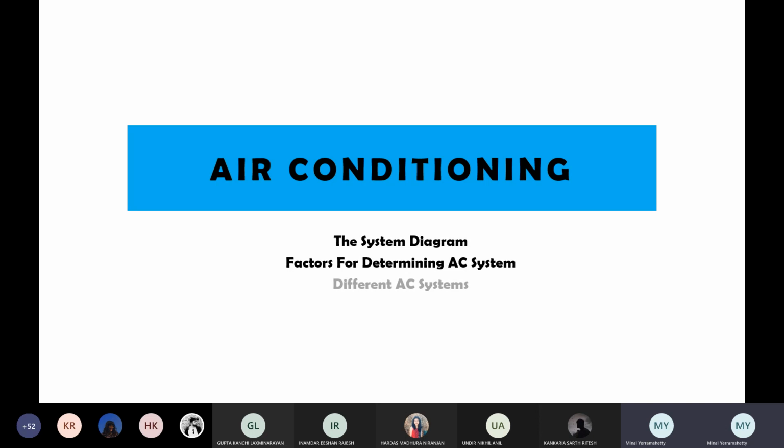अगर है तो आपको वो chilled water, which is the coolant, the degree of that water is around 6 to 8, 10 degrees. Okay, you need to take that chilled water to wherever respective places you need to go. Okay, where again the heat transfer happens, it gives away all its cooling to the AHU and comes back again in a normal form. Okay, फिर से वो ठंडा होता है, फिर से ऊपर जाता है, and that cycle also continues simultaneously, 24/7 if the building is working 24/7 continuous. ठीक है, तो ये होता है तुम्हारा 3 cycle.